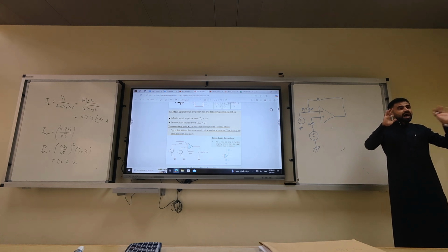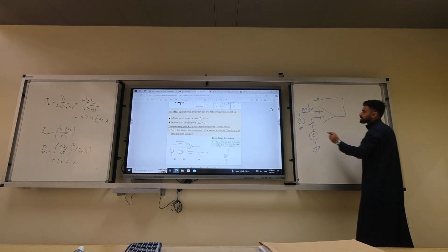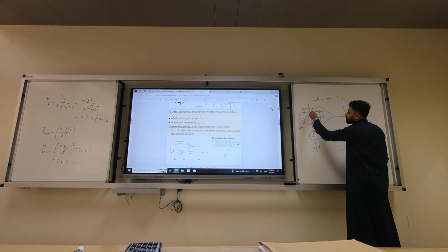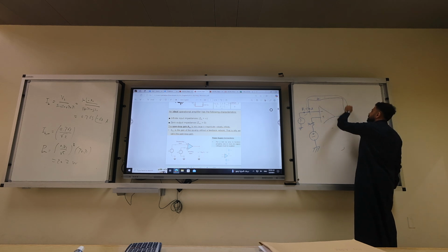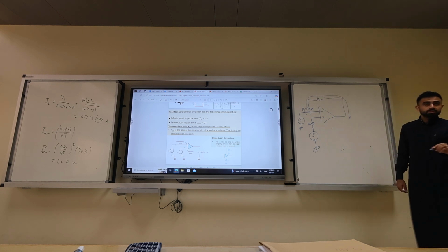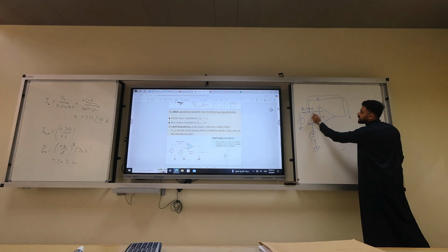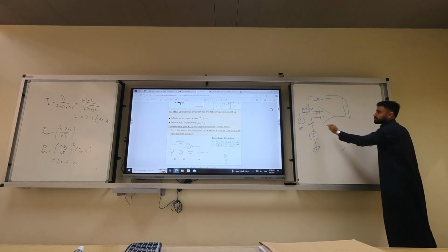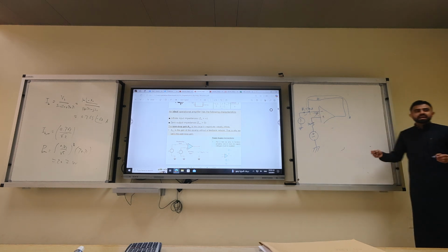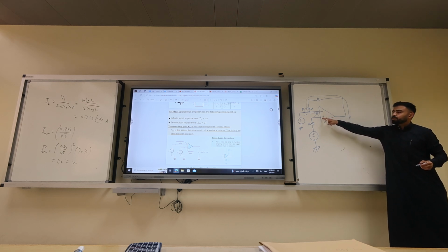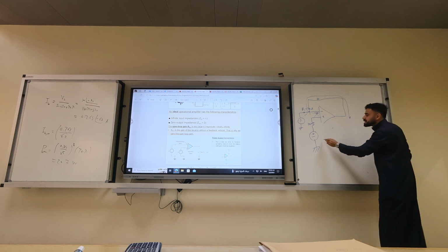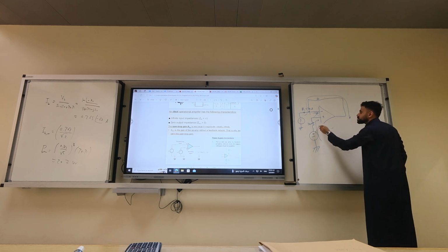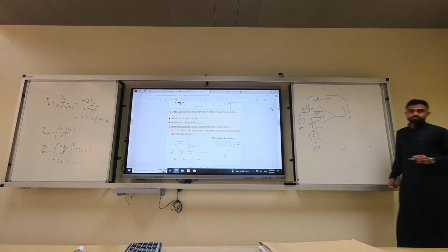What I mean by high input impedance is the voltage here would force all the current to go outside here, okay? Meaning no current is allowed to go inside. What does this imply? It means there is no way a current will be here, so I equals 0.